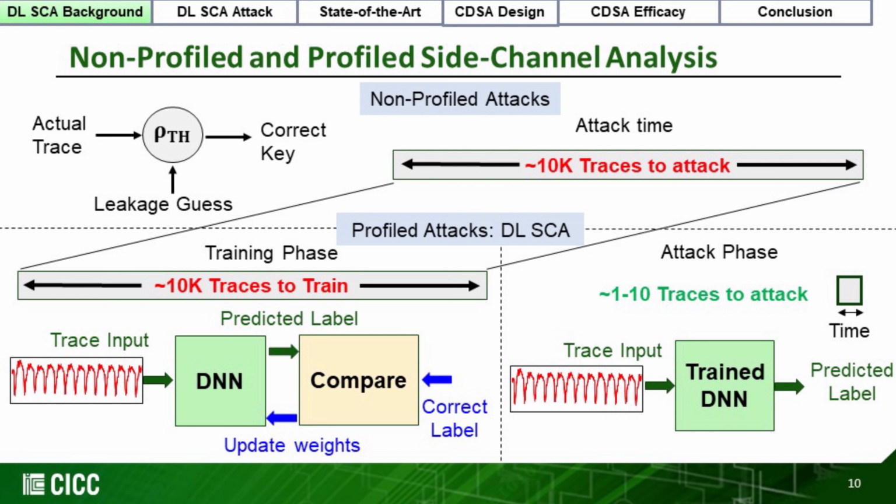The attack succeeds with as low as a single trace, which increases the threat surface for embedded devices significantly. Compared to the statistical template-based profiling attacks, deep learning frameworks are more automated and would aid an attacker mount successful attacks on crypto implementations without prior knowledge of the architecture.